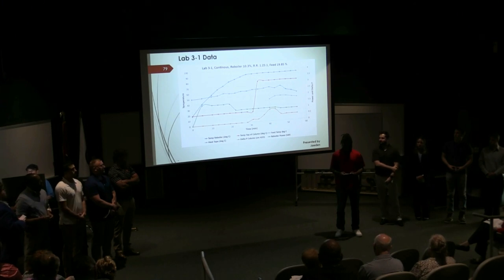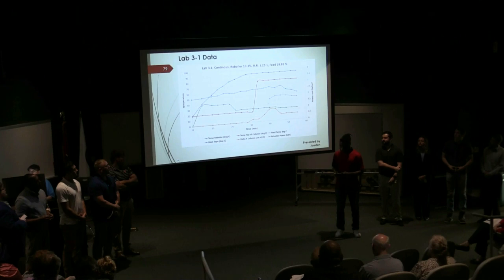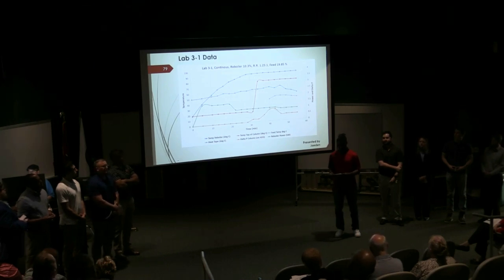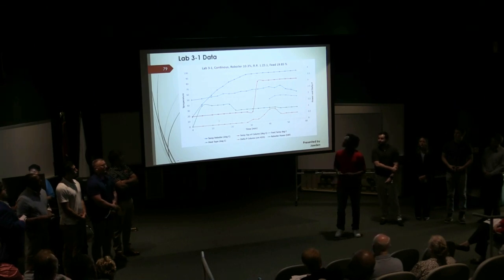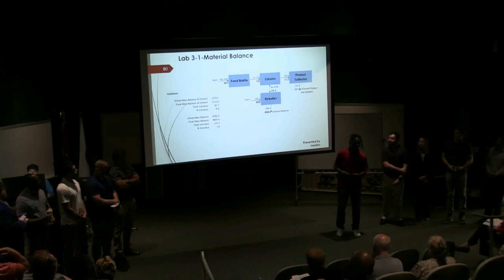In our first experiment, we had a heat tape setting of 30%. If you look at the experimental data, you'll see 2 additional curves: a heat tape temperature and a feed temperature. Looking at the curves, it appears that the experiment was stable based on the minimal rise at the top of the column. We did have to make one reboiler adjustment. According to the pressure drop curve, we had higher production in the beginning of the run. And then we closed all our material balances in the desired range.